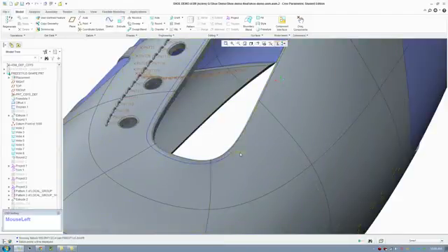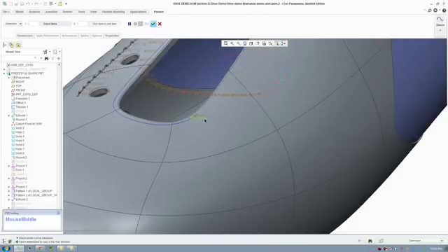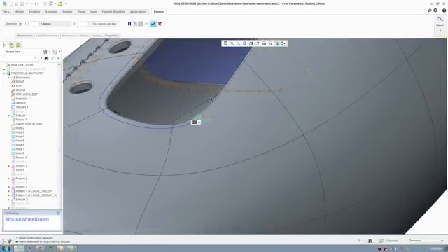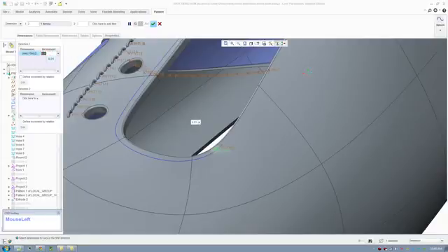So if you select that point, go to pattern. In this pattern, if you select this relative positioning, we can put the size for each pattern. So let me change that. Make each increment 0.03, and we can put in the numbers.